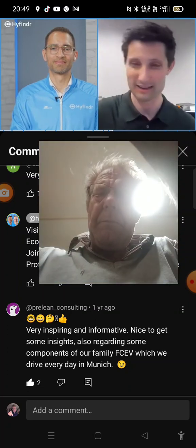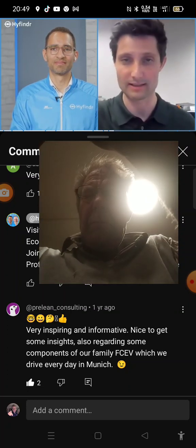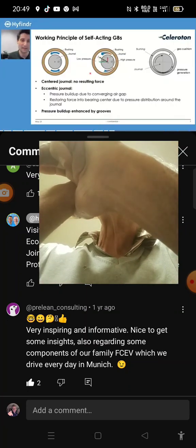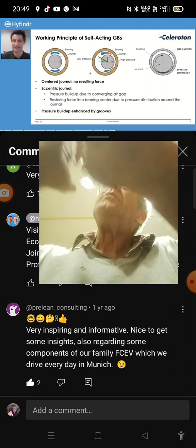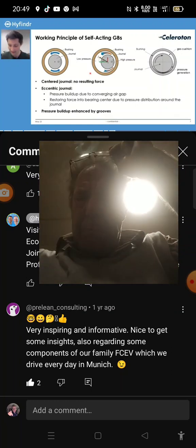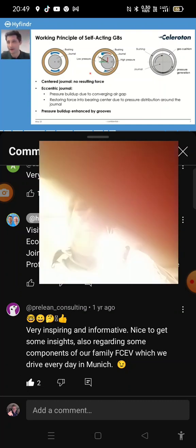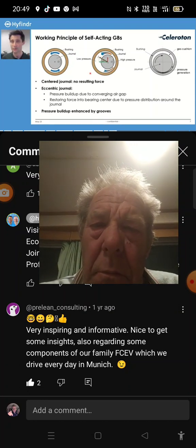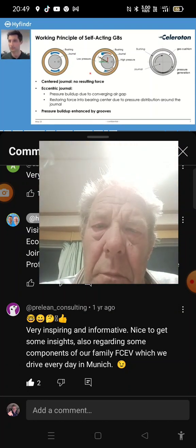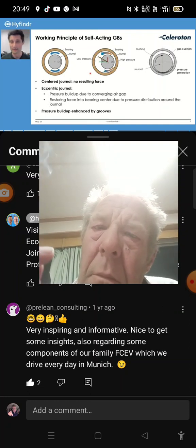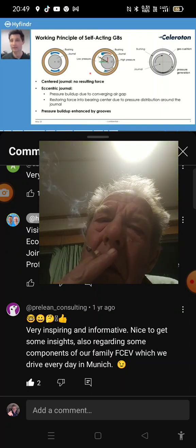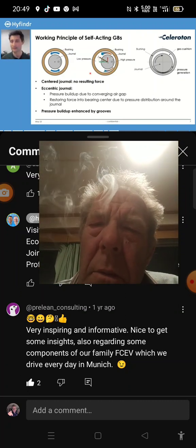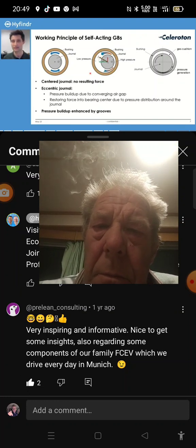Yeah. So I have to check whether I have a slide that I could show you. Yes, here we go. So let's dive into the details of gas bearings. I mean, gas bearings are very interesting. Generally speaking, one can differentiate between hydrostatic and hydrodynamic bearings. For mobility applications, which is the most current case, for instance, for road applications or aerospace applications, hydrodynamic bearings is the one that one uses. Reason being, simplified design, few external parts, and so on.